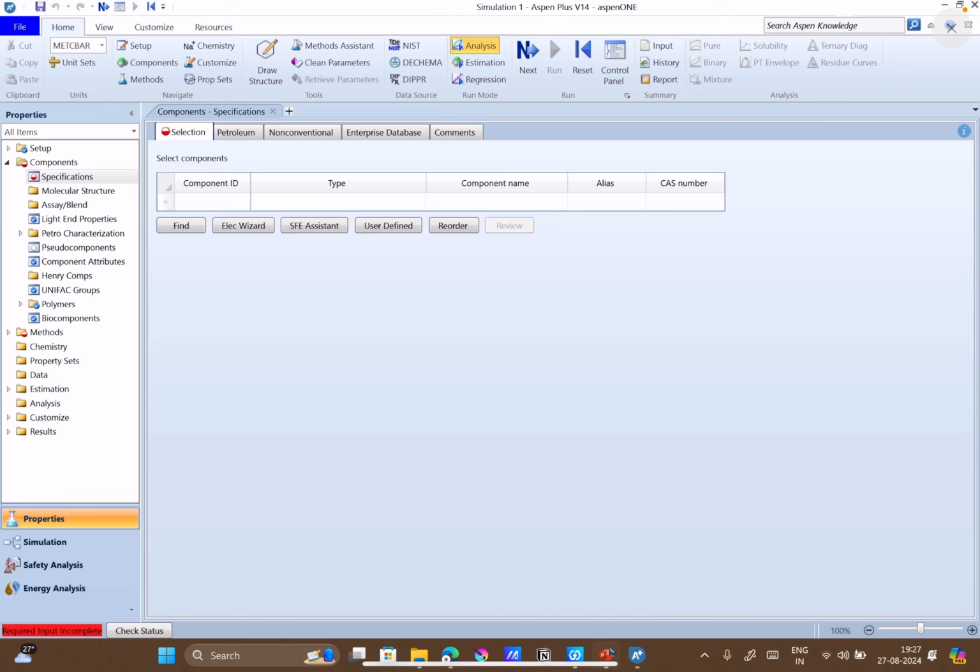Okay. Now coming back to the question of Shailendra, so can you change the order? What you do is go to home. Again click on ternary diagram. Okay, continue to Aspen Plus ternary diagram. So let's say we want to first put MIBK and put acetic acid later. Yeah, and just run the simulation with 10 tie lines.